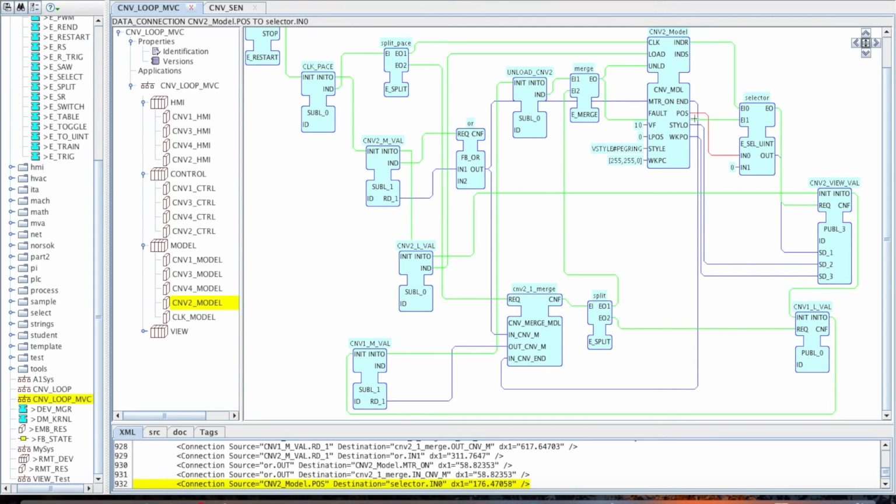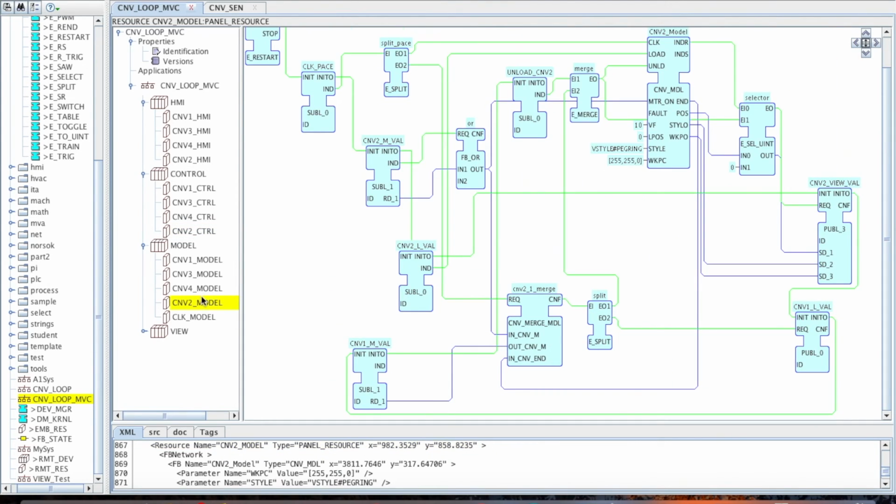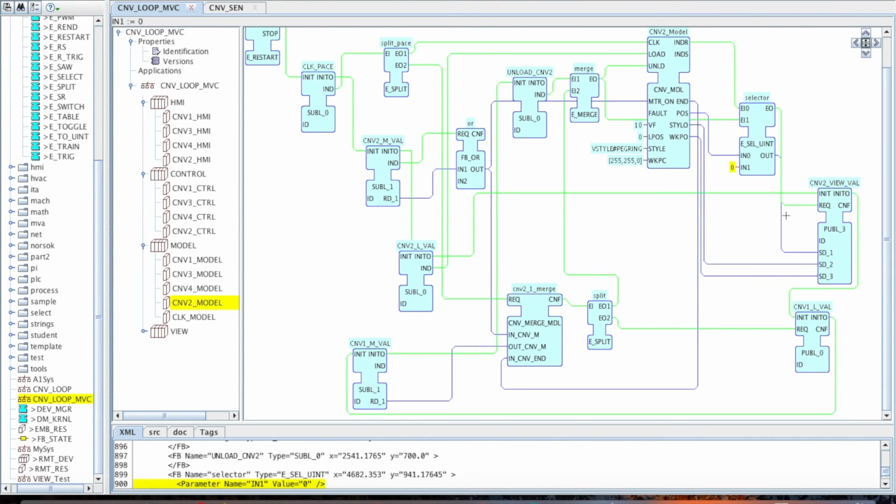It's not reset. If the unload event is coming, it's not being reset, and therefore the corresponding sensor may think that the pallet is still present. So here is a small hack implemented on the model level, a selector block to put 0, so 0%, as there is no pallet in principle, or workpiece in principle.